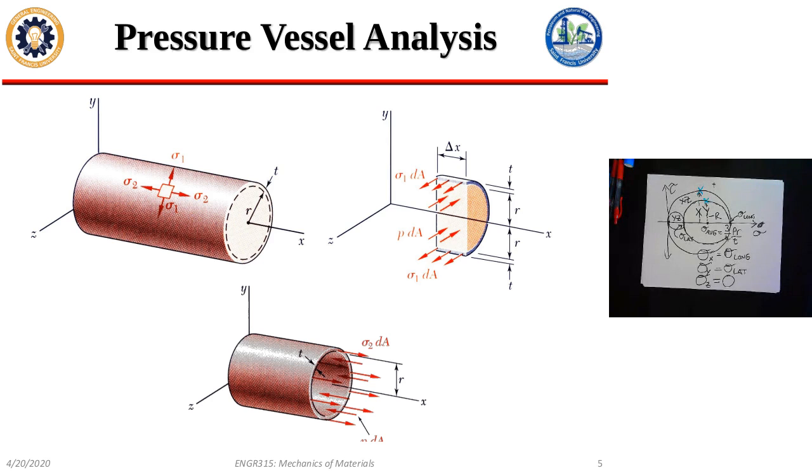So it's necessary that I not just consider the 2D Mohr circle in order to predict failure, but the 3D Mohr circle. Even though I don't have any shear stress in my XY plane, and even though I don't have any stress in the Z direction, the maximum shear stress on my 3D stress cube is highest in an out of plane direction.